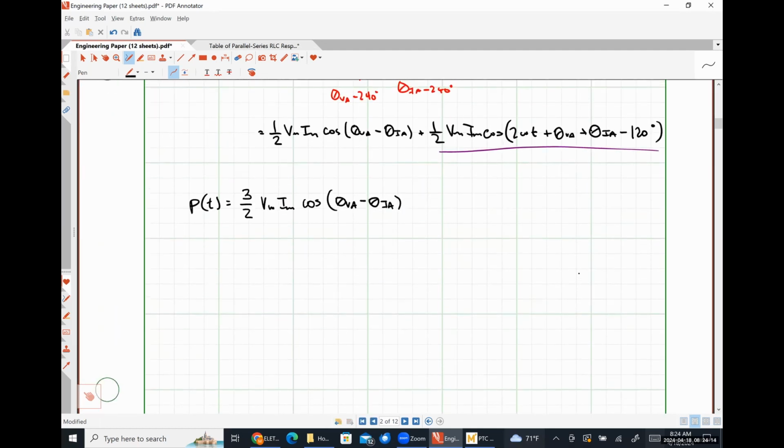So this is instantaneous power, and it's also given us a clue about what's going to happen when we look at our average power, because this is very obviously P average for a three-phase system as well. It is just the DC component of our instantaneous power. Okay. So now let's look at things from a different perspective. So now we're going to look at complex power.